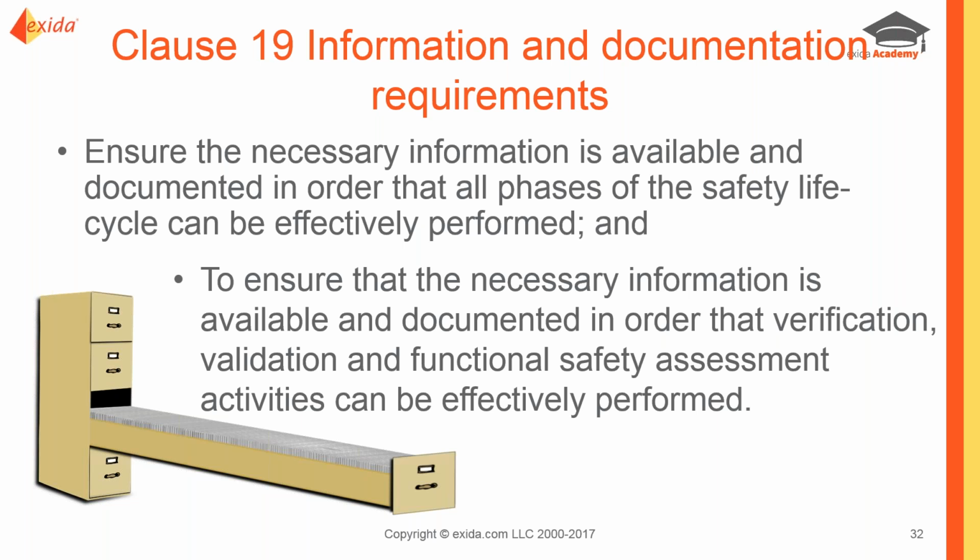We also need that documentation available for that verification and validation stage at the functional safety assessment, because early design documents that define the basis of what the SIS should do is what we test against when we're doing those functional safety assessments, the verification and the validation steps.